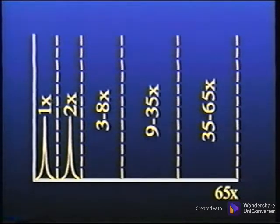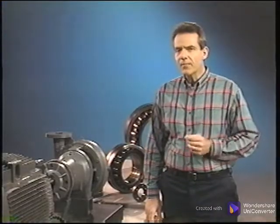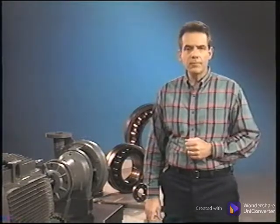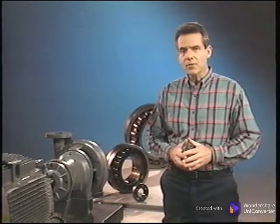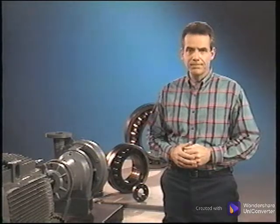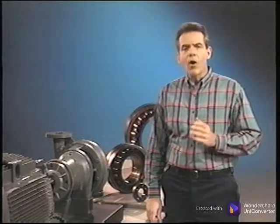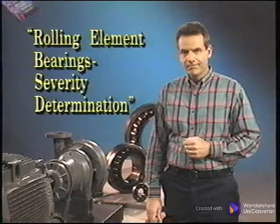This last band is in acceleration and is outside the parameters of the stored spectral data and is only a trended value. Again, realize that these recommendations are for normal garden variety pumps, motors, fans, and so on. Special applications such as high turning speeds, above 100 hertz, or extremely slow turning speeds may require special settings. Explanation of these bands and recommended alarm levels for each band are covered in the program Rolling Element Bearings, Severity Determination.